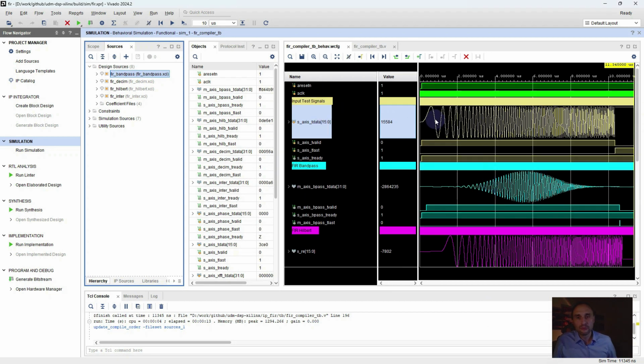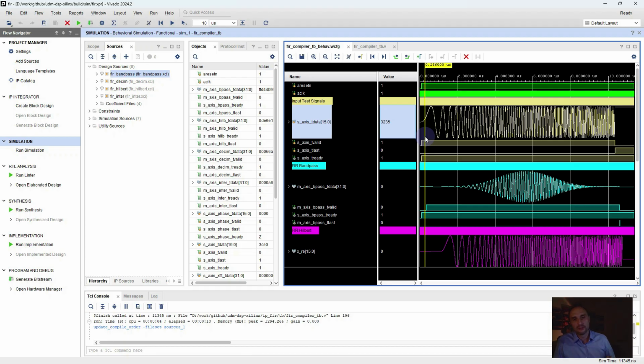This is the input file. As input signal, a chirp signal is used, with frequency started from 0 MHz up to 20 MHz. Therefore, the bandpass filter will pass only frequencies within its frequency response, and it can be seen in time domain here.